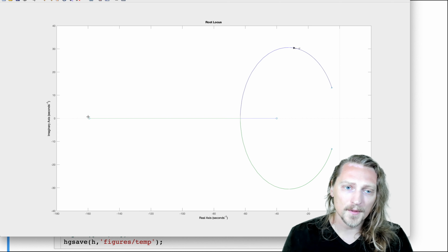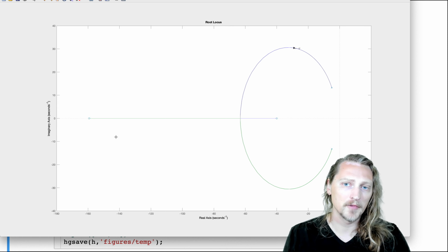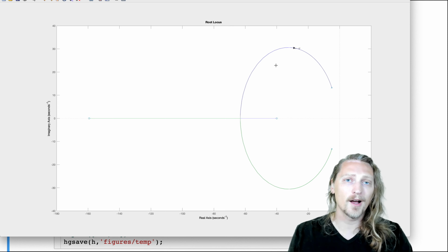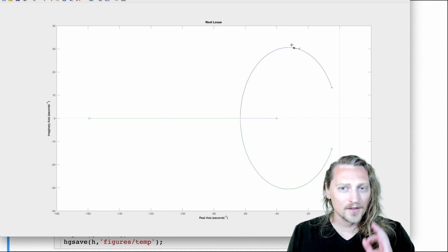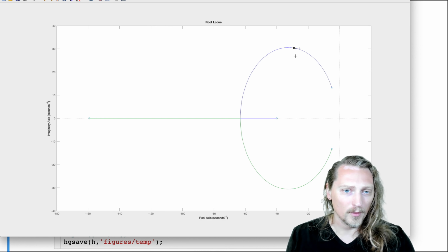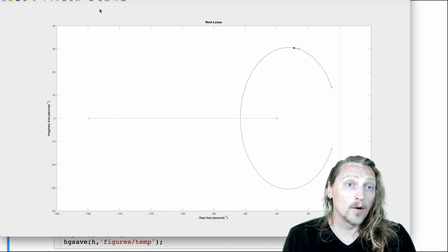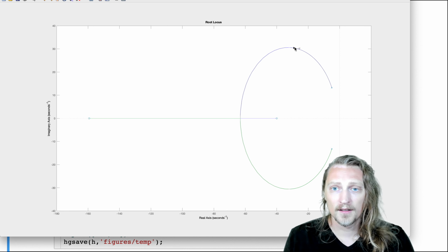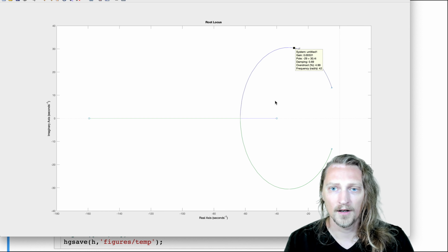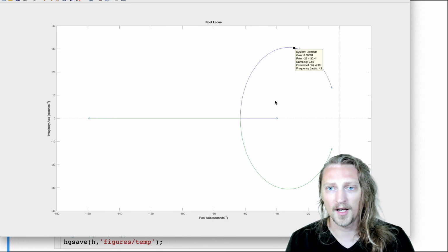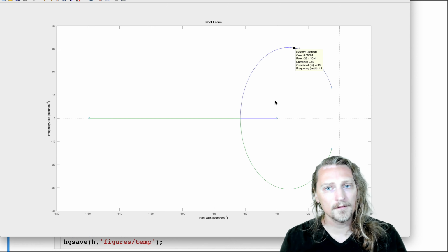And we see that zero compensator showing up way out here. It moved things around in the root locus so that we were able to go through that design point. Great. Derivative compensation is working great. Now we could adjust our gain and try to get right on the design point, which looks like it's going to be about 0.005 for the gain.